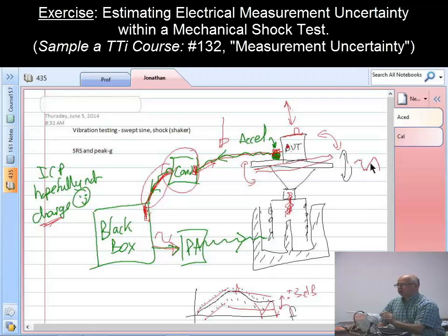My only other concern then would be harmonics, because it's all locked into constant frequency, and so nonlinear harmonics. I'd just essentially look at the spectrum and say, if my spectrum of my signal here is a nice clean something like that, I'd say, okay, harmonics is not an issue. If I had something that looks like this, I'd say, well, that's probably okay. But if my spectrum looked like this, I'd say, oh, I have some serious issues with harmonics.